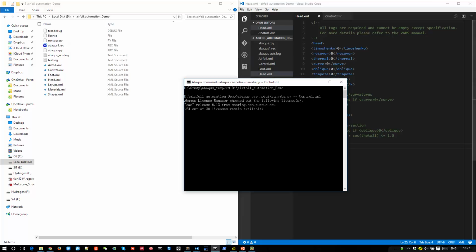On the backstage, the code will first create a cross-section model, then generate an Abaqus input file and convert it to VABS input, and finally run VABS.